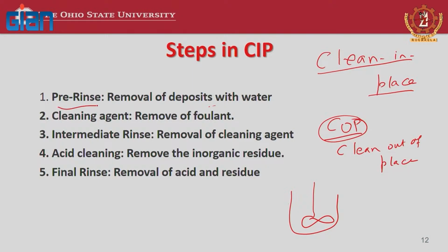It is called the pre-rinse. This does two things. One, anything readily dissolvable is removed. The second is, in case you took some time off between processing and starting your cleaning cycle, anything dried out will be hydrated, so that it is easier to remove in the subsequent step.